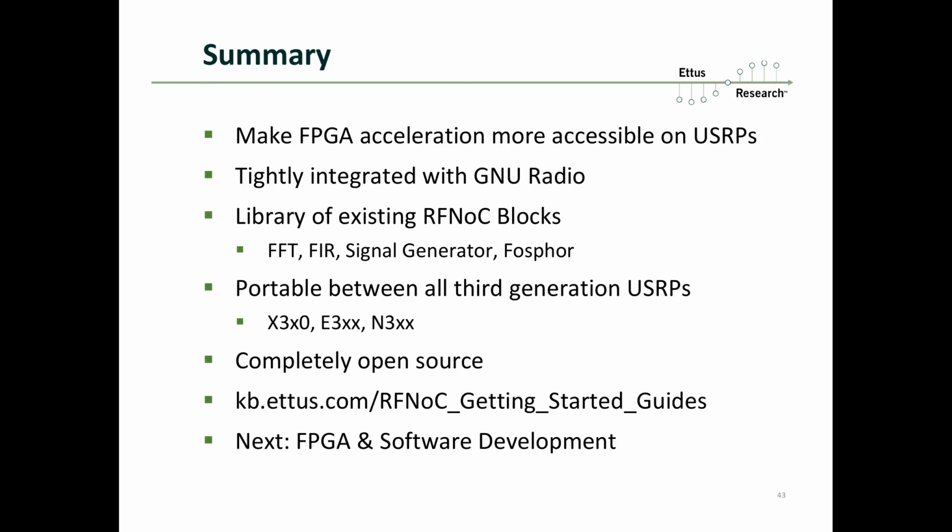RFNoC is supported on all current third-generation devices, such as the USRP X300, X310, N300, N310, N320, N321, E310, and E312, and will also be used on all future devices going forward. And again, the RFNoC framework as well as the host side UHD driver are completely open source.